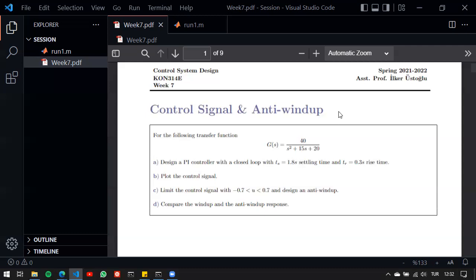The same applies for other types of systems. One of them could be the acceleration limit, again, on the vehicle, or you might have a voltage limit or a current limit. So what if we have a certain limit on our control signal? Now, up to this point, we've used linear systems. Therefore, the implication was that if I have a relation between output and input, I can apply infinite input and get infinite output, which is not possible in the real world. So today will be all about this limitation, or saturation in other words. So we'll use a saturation on our control signal.